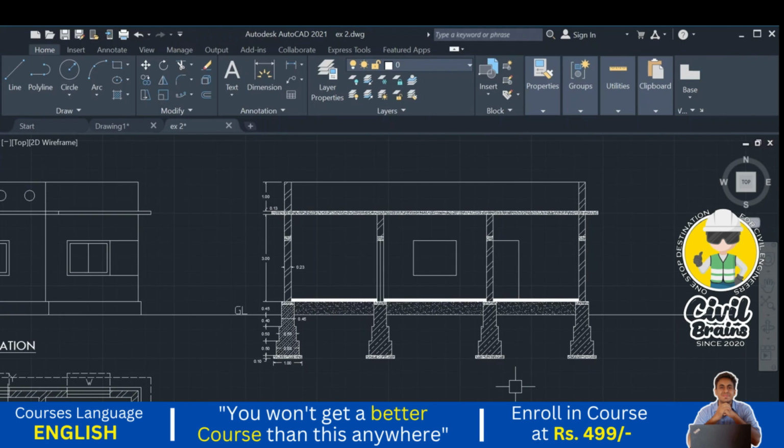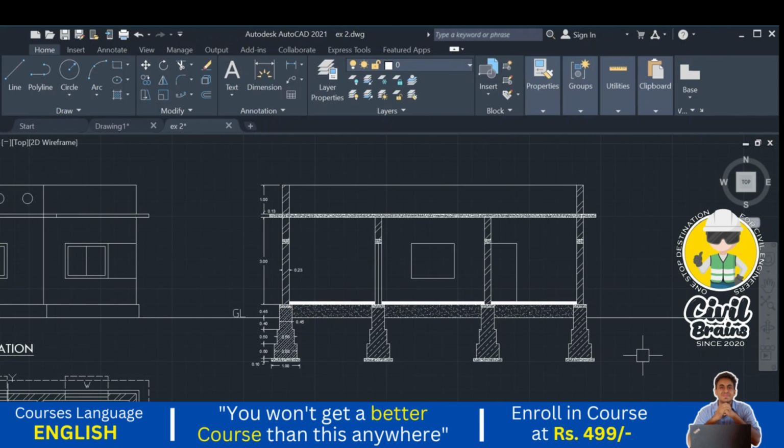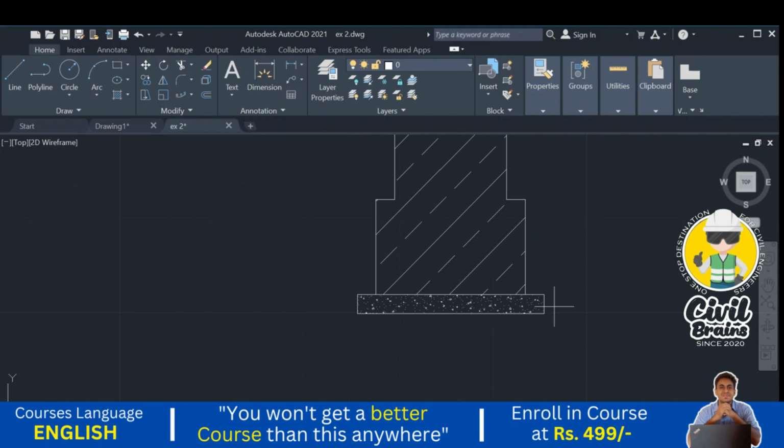Now we need to show the naming. We need to do the naming for all the structure, all this one. I just go to the leader command for the naming. I just use the leader command, it will be easy. I just click on the leader command. Here it is asking specify the point. This is our point, first point.